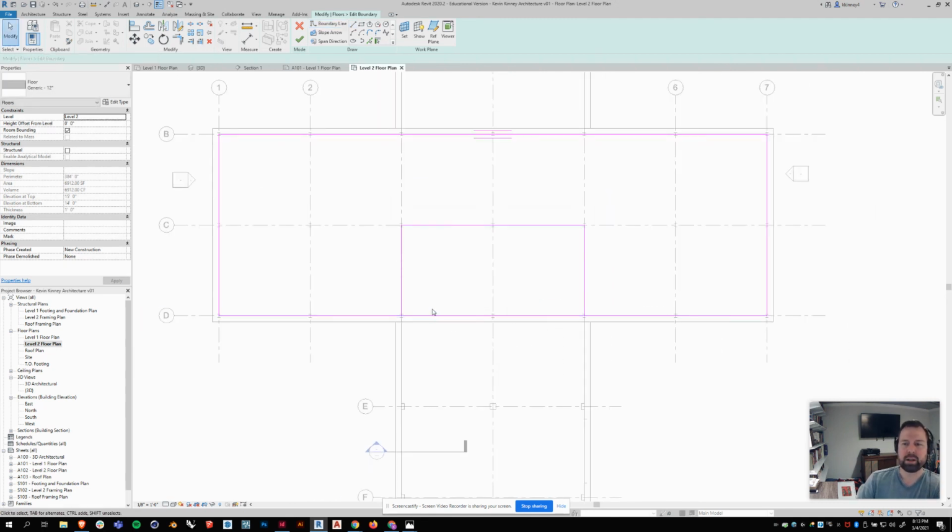Now, this isn't a correct drawing. It will give me an error, okay? Because I have to cut this portion out. It has to be one continuous line that defines the whole floor plate. It can't be weird like this. Let me show you why it's weird. If I trace this line around, everything's looking good. Yep, one line, no big deal.